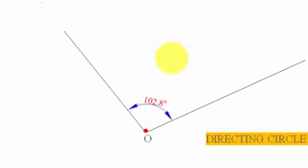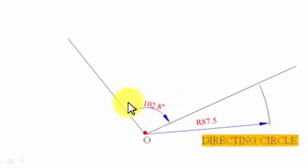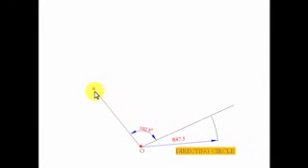Alright, let's start again. This is 102.8 degrees, this is 87.5, and this is the point P which we'll be keeping a track on, and above which we'll be making this rolling circle. Let's draw this. So okay, you can produce this line, and this distance is going to be 25 millimeters. Okay, and this automatically qualifies as the center of the rolling circle. Fine. So let's have a rolling circle. Alright. Now perpendicular to this line we have this line over here, and perpendicular to this line we're gonna have one more line, and let's move ahead this way.